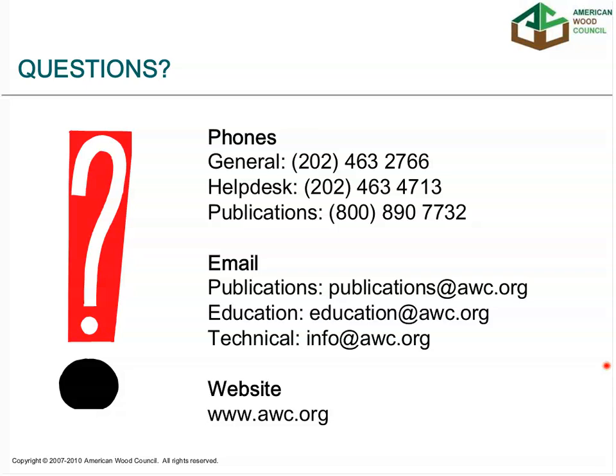Okay, no. The wet service condition is anytime the wood member exceeds 19% moisture content. And so that can occur even with rain or high humidity environments, if they are sustained for any period of time. And we're getting deluged here on the East Coast the last couple of days with about 2 to 5 inches of rain. So any type of wood member or connection that's exposed to rain on a continual basis would be considered a wet service application.